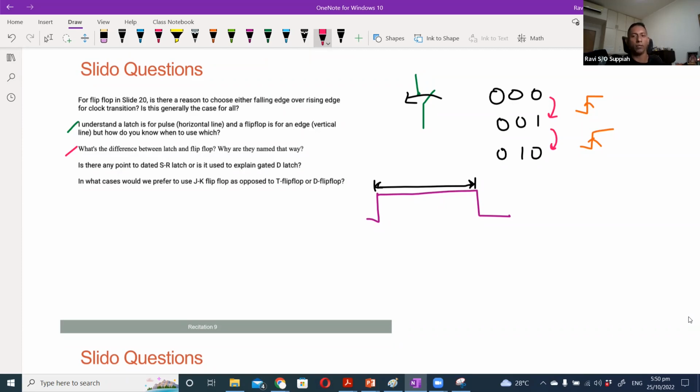That means when the active clock triggers the system, it takes the current input and the current state to generate the next state and the new output. Whereas in a latch-based circuit, as long as the latch is active, it will keep updating the output if and when necessary.